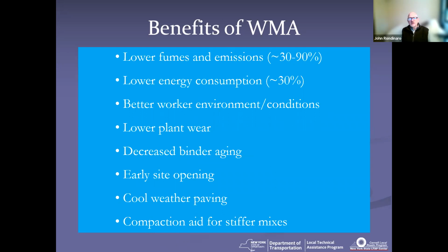You've got the opportunity for cooler weather paving. A lot of states are investigating this or looking at that real close. And then finally, for any kind of stiffer mixes that are being used, you can even use, or you do use that WMA technology just strictly as a compaction aid.